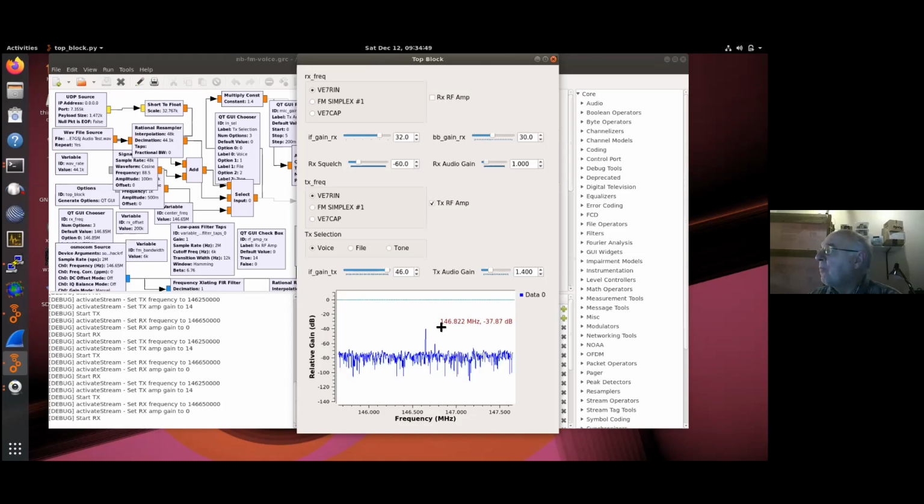So it's very common when you're using an SDR, the center frequency for receive, you try and set it about 200 kilohertz away from the signal you're trying to demodulate. Because if your signal was right here, you're doing frequency demodulation, it would be desensitized by this big DC spike.